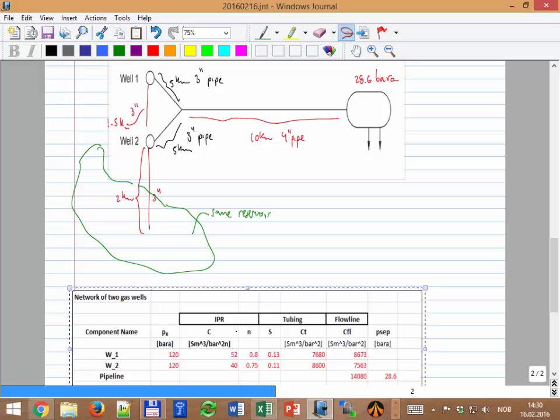Also one comment that I want to make. This gas equation that we are using is usually for low pressure. When you have high pressure, you cannot use the pressure right away in the equation, but you have to use a pseudo function, the m function. How many of you have seen that before in your courses? 1, 2, 3. Yeah, if you want, I can put some references on its learning.